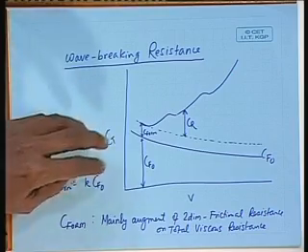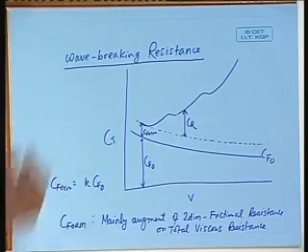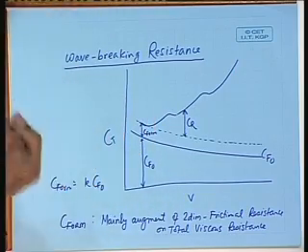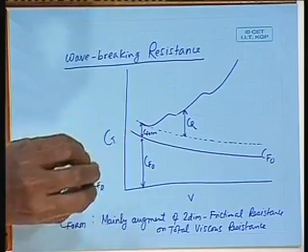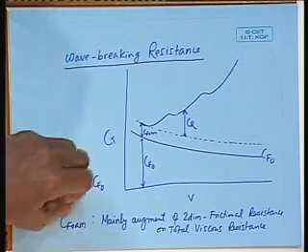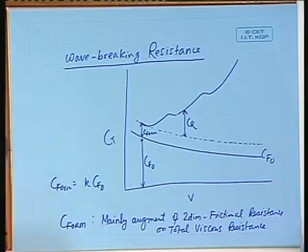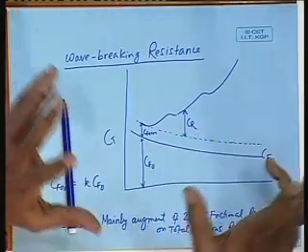Okay. So, we can say C form includes the 3-dimensional friction form effect, and it also includes some amount of separation drag component and viscous component. Imagine separation, we have said, is related to velocity and pressure, so it will change with the velocity of the ship. If it is something at low speed, it cannot be the same at high speed. So, truly speaking, we have not taken this totally into account. That is why I am saying "mainly"; the word mainly is important there, it is not total.